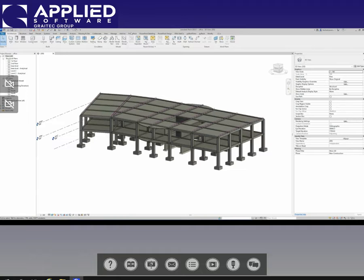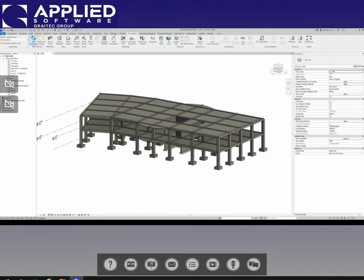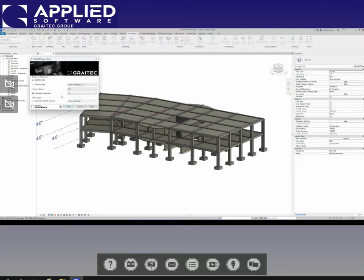I will go to our Power Pack tool there. As you see here, we have a Beam Connect tool that you can use to export, import, and synchronize your models through Revit and send them to Advanced Design. In this case, I'm going to be exporting my model, so we click on Export. As you see here, we have some parameters that we can define, for example, the types of loads that we want to export to Advanced Design. Also here, we have an option that you can select, and after export, it's going to automatically open Advanced Design. In this case, I will just keep everything as default, and I click OK.